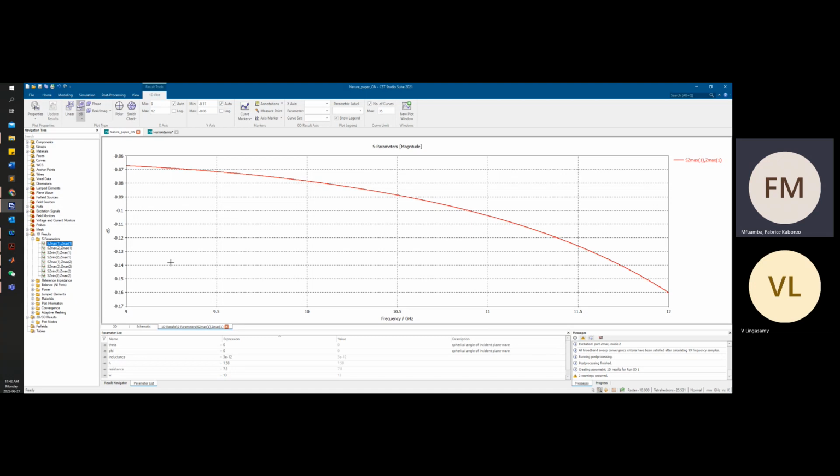So my first question is, the Z max 1 is for XY polarization, and the Z max 2 is for X polarization. Is that true? Exactly. So one for horizontal, one for vertical, if you are exciting two modes. Here the max is for port one, ideally S11. Z max means it is S11. If it is Z min, it means S22, like that, port number 2. That way we have to correlate.